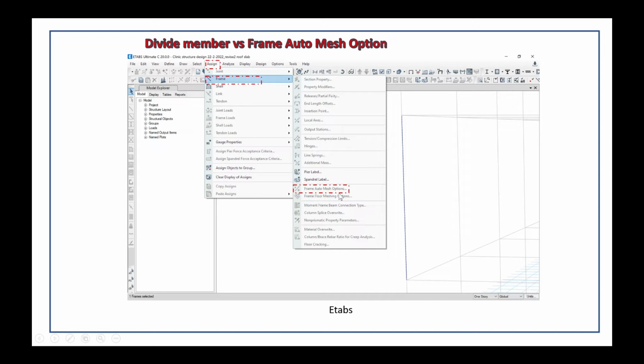You will get a better result, including all the analysis results, bending moment, shear force, with the deformation of the member. So the option is really good for you for the long column. You are concerned about the slenderness, about the small P-delta. You can use the option.